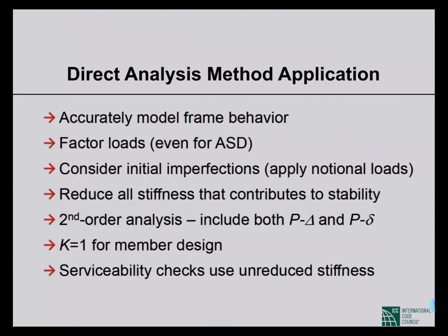So these are the points that we have to remember to apply direct analysis method. We have to model the frame behavior accurately. So this is not so difficult. We are used to modeling using finite element method based software. So if we model in that fashion, that is okay. That is the accurate model. But if we go for 2D analysis, a few years ago, many designers of steel structures used to model 2D frames and then analyze. That is not accurate. That causes problems.